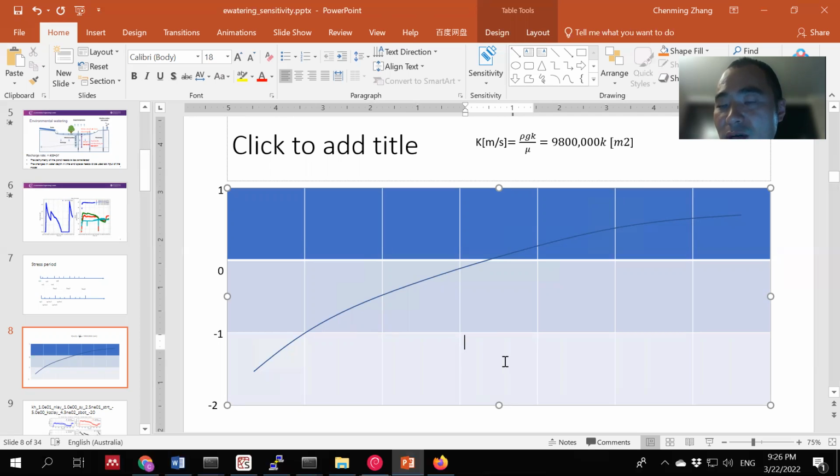If you try to put in 0.1 millimeters of water, the hydraulic head within that cell will increase by 1 meter. So that's just an indication. So three different types of cells. There is no unsaturated zone within MODFLOW. If the cell is above the water table, it's considered an inactive cell. But we have the UZF package, but that is for very specific conditions.